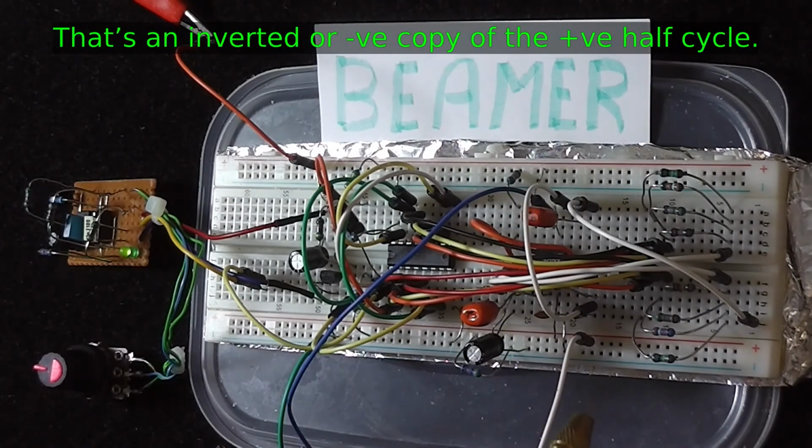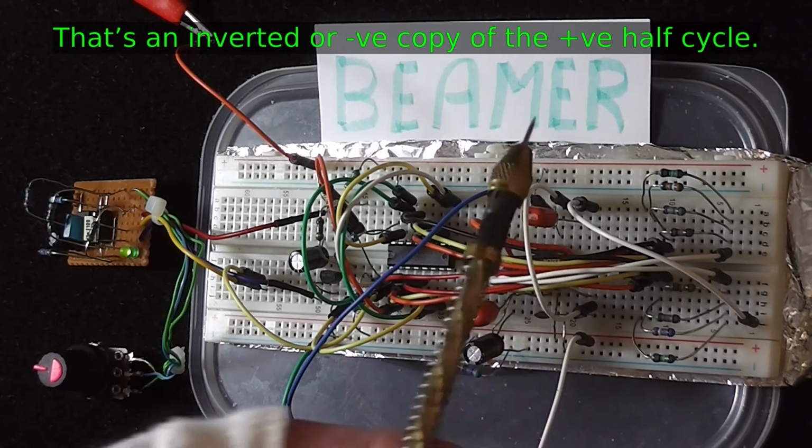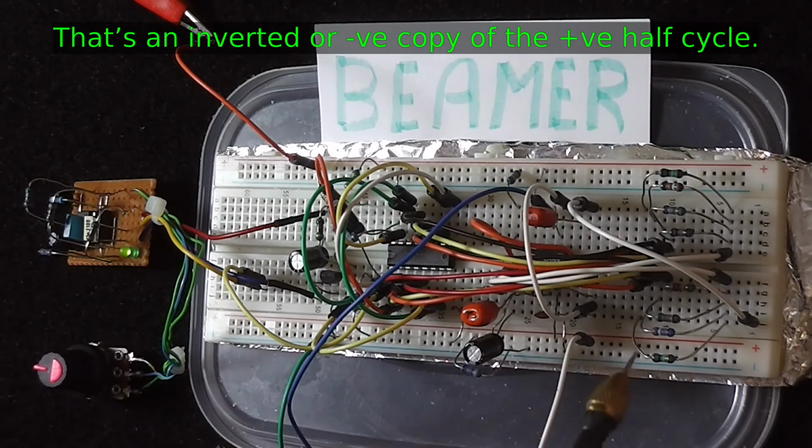These resistors are the resistors that define the wave shape, and you change them accordingly. You can remove some resistors, leaving gaps that create one type of waveform. I've even added a diode across one of the resistors to form another wave shape. So there are many permutations that these resistors define.